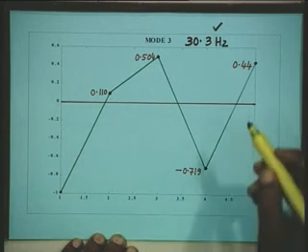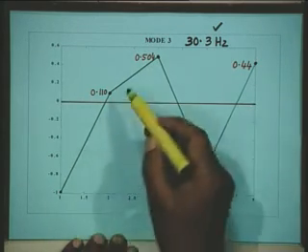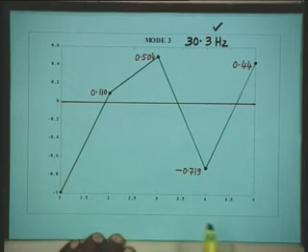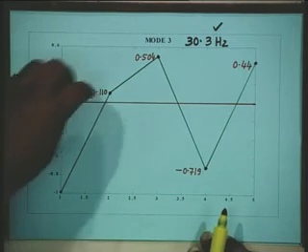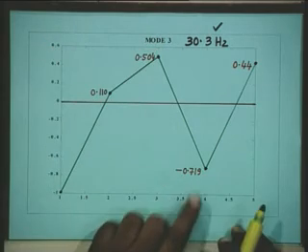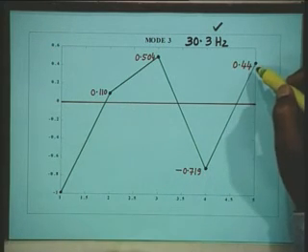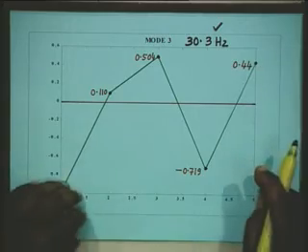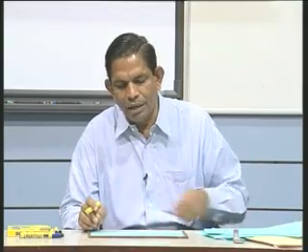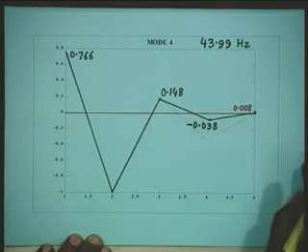And again now we can easily see here that when the system is perturbed, we will find actually that the mass 1 will oscillate with respect to mass 2 and 3, and 2 and 3 will oscillate with respect to mass 4, and 4 will oscillate with respect to mass 5, and so on, right. Similarly, the mode shape for mode 4 is shown, and you can easily see that there are 4 crossings.